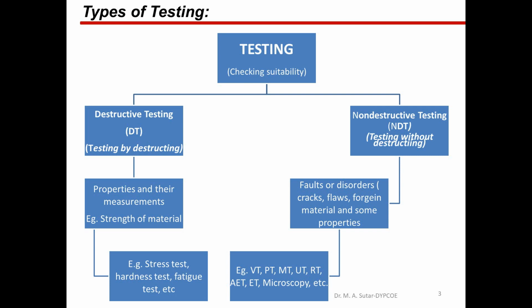There are two well-established testing methods. One is destructive testing and another is non-destructive testing. In case of destructive testing, there is testing by destructing the material, whereas in case of non-destructive testing, the material is tested without its destruction. And that is why material can be used after testing also. That is one of the most important advantages of non-destructive testing.